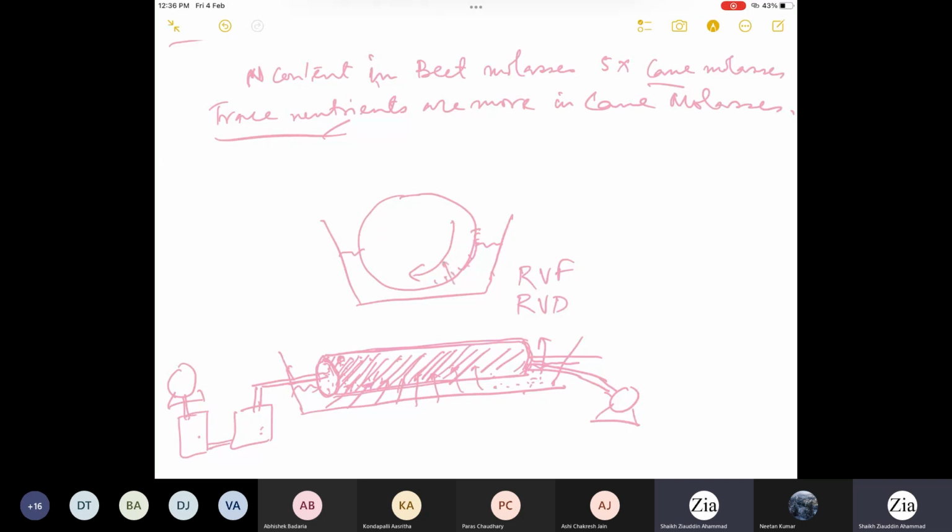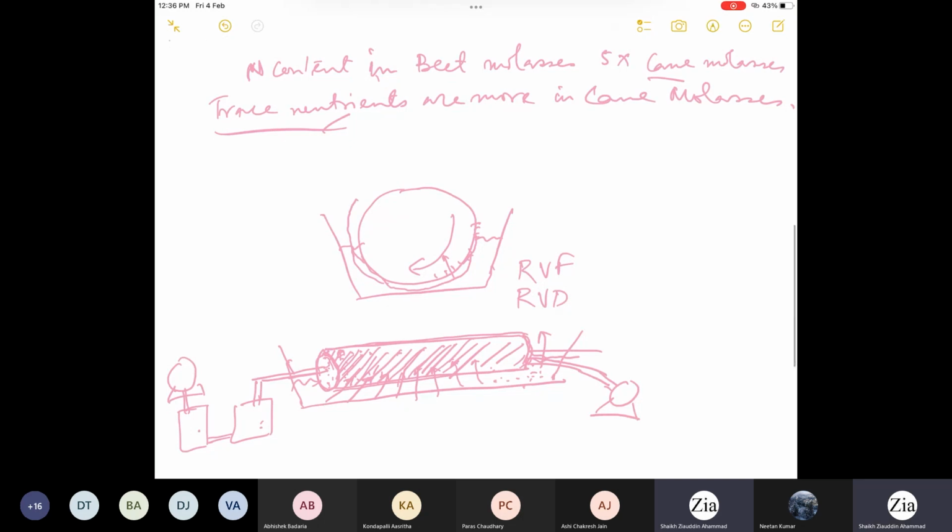Liquid will go in, but solid cake will deposit, and slowly, when it rotates, the disc cylinder having a solid cake layer on the top will come out of the liquid. Here we will first put some jet spray to dislodge the residual liquid present in the cake.